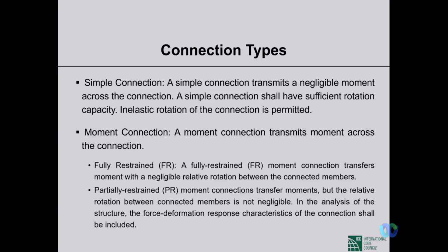However, since it doesn't transfer the moment, the connection itself goes under rotation. We have to be sure that simple connections have sufficient rotation capacity, and inelastic rotation is also permitted in case of simple connection.